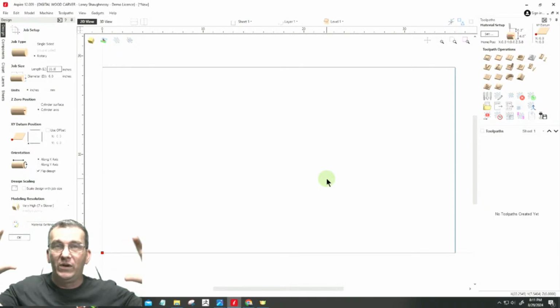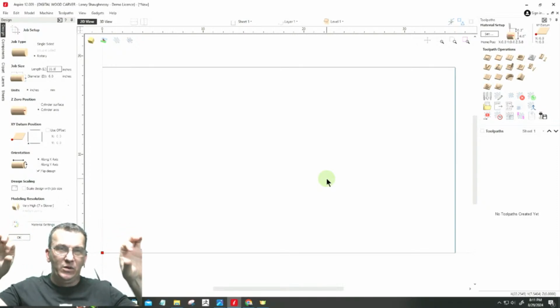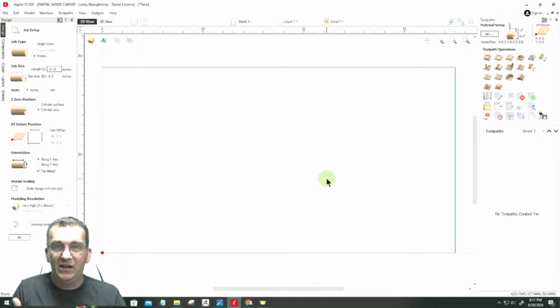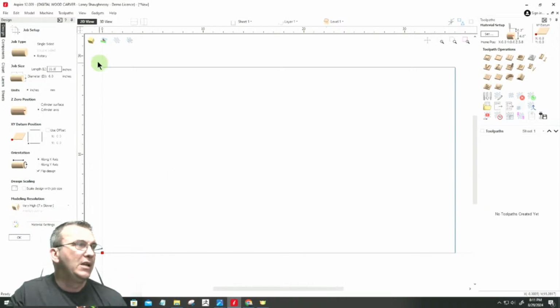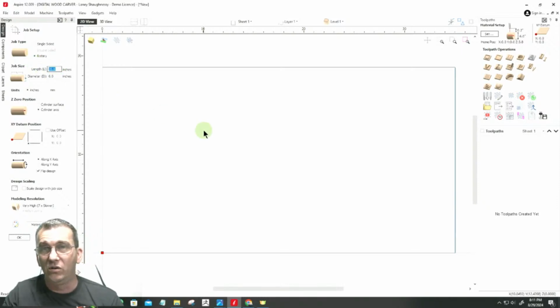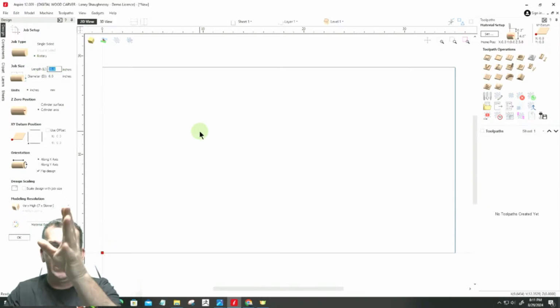Because if I'm doing a rounding toolpath, or if I'm milling away down to a small dowel or something, I don't want to run into my tailstock or my spur drive or my jaw chuck or whatever it is that's holding my part, right? So what I like to do is just make sure my blank is longer, and I'll measure and mark at the table. I don't account for the waste in my design, but it's up to you what you do.